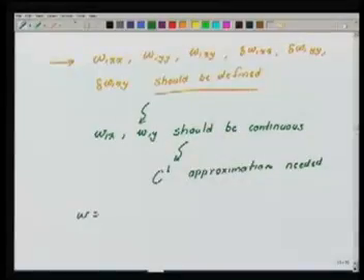Similarly here we could have on the boundary the slopes or the rotations del w del x, del w del y defined. In that case the del of delta w del x and/or del of delta w del y should be 0 correspondingly. That is, in terms of the slopes also we will have geometric constraints, just like we did in the Euler-Bernoulli case.